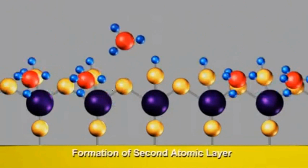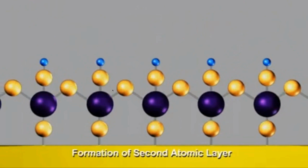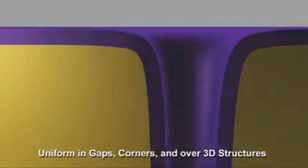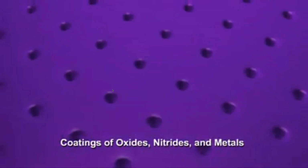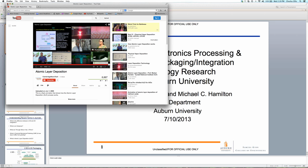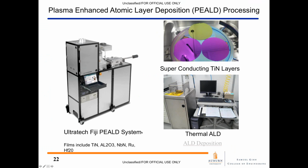You then put in, in this case, water vapor that removes the ligands that are on the molecule, and then you repeat the process step by step to get as thick a film as you would like. And again, this little video just shows you a thermal ALD system that Auburn has here also. And we can put down films from titanium nitride, which is superconducting and also a barrier layer for TSVs, aluminum oxide, niobium nitride, ruthenium, and hafnium oxide, and we're working on some other films.